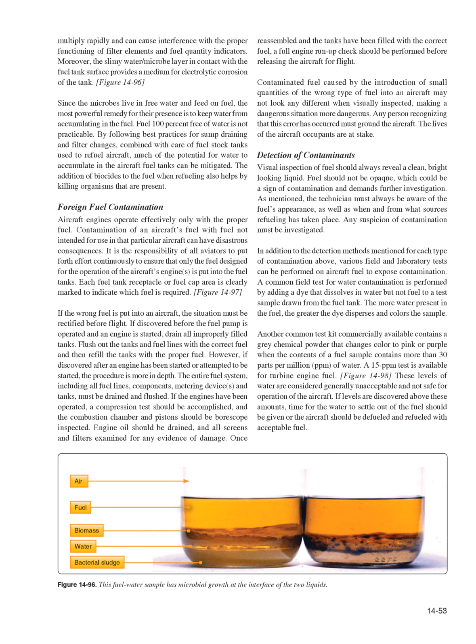If levels are discovered above these amounts, time for the water to settle out of the fuel should be given, or the aircraft should be defueled and refueled with acceptable fuel.